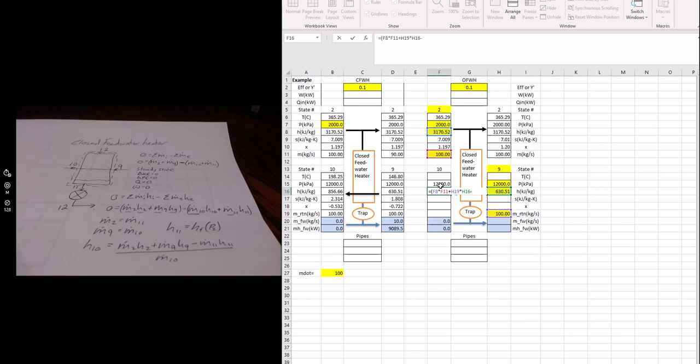So both of these terms, I'll leave that one for a minute. This one would be this fraction times the one it's a fraction of. So we're saying take 10% of this, so that's that mass, and then that is going to be the same value, so it's equal to that times that, so that same fraction of flow times the enthalpy, which is the enthalpy of saturated liquid.